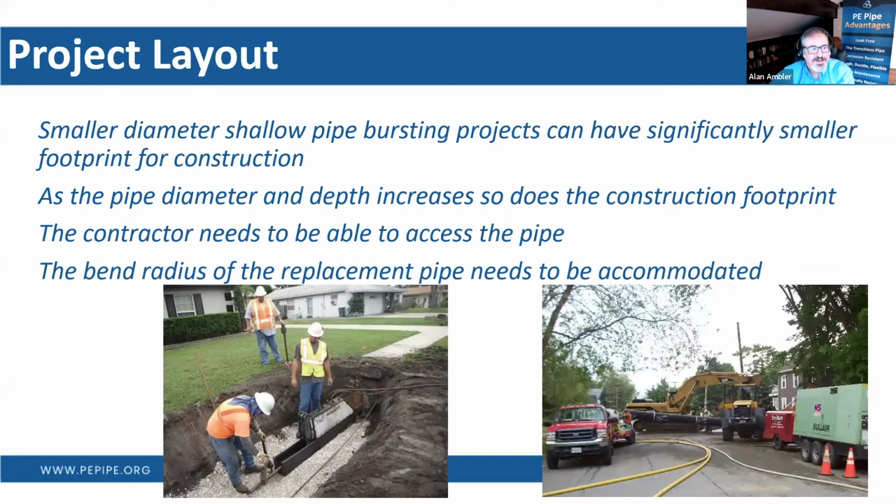It's wonderful. Project layout here. Obviously, as we get bigger and bigger with the equipment and the pipe, the site layout needs to be larger. So you'll see here in comparison, very small pipe bursting rigs, since we have very shallow depth and very small pipes, and then a larger rig where they just decided to shut down the entire road to provide access on a pneumatic pipe bursting system.